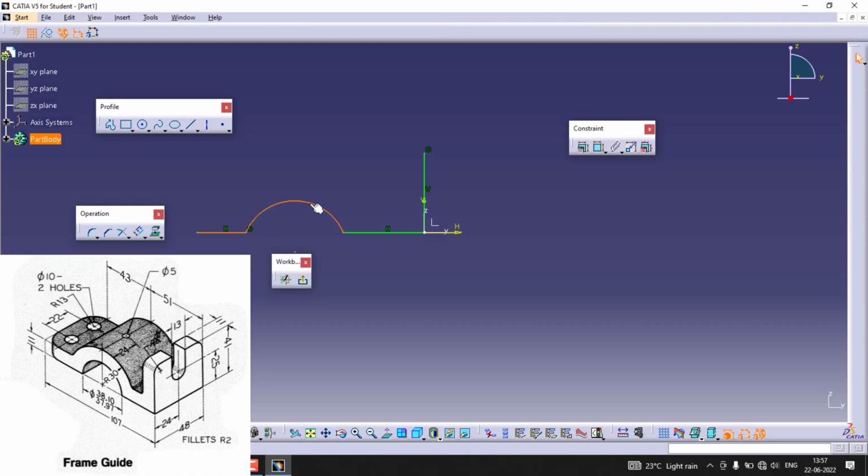Just select all the entities. Okay, hold the control and just try again and offset it. Yeah, so you can just hover first towards the top, and then you can directly go at the offset and distance, mention it. Okay, 11. That's all. Now by using the line tool, you can simply close these open profiles.